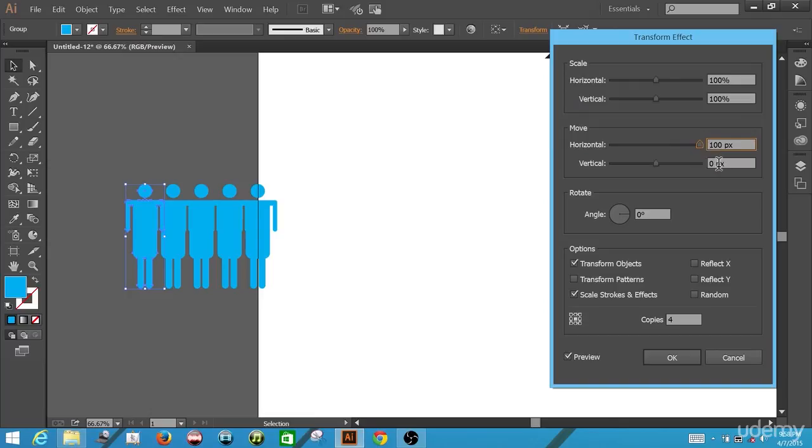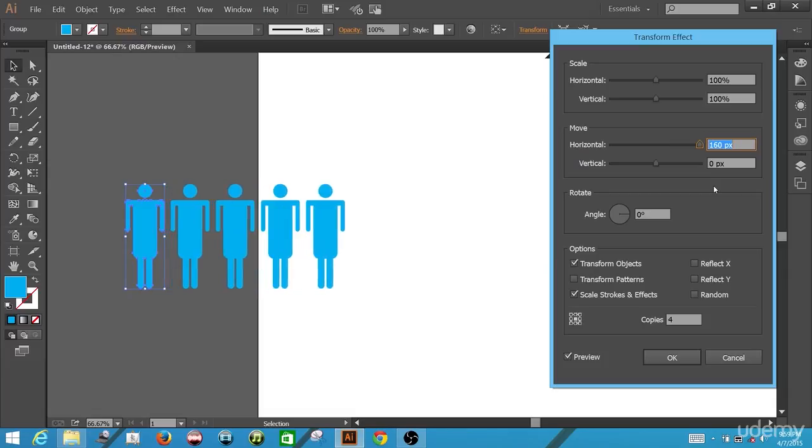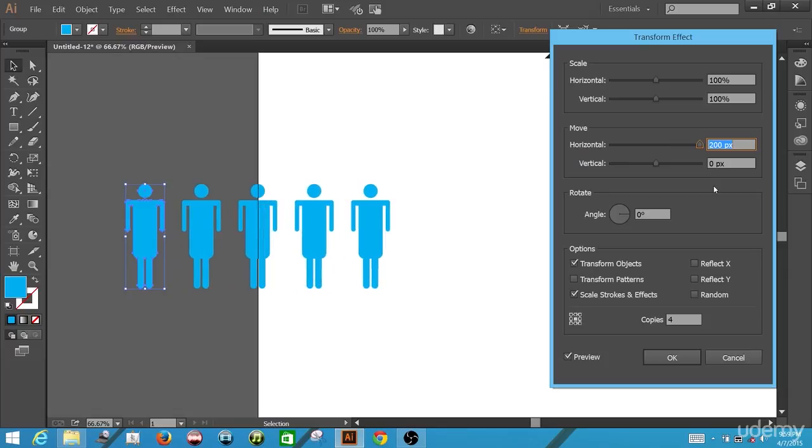I'm going to need more spacing, and I have reached the extent of my slider. So what I'm going to do is I'm going to go ahead and hold down my Shift key, and while holding it down, press a couple of times on my up arrow key. And that is good spacing. Release Shift key, come down here and click OK.